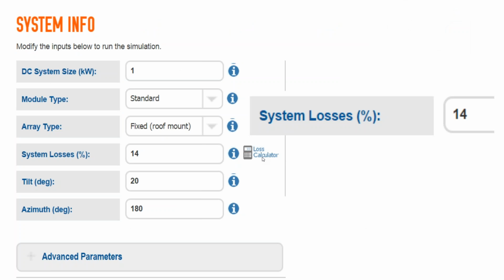So working up to our PVWatts example, here I always do a 1 kilowatt solar array. Again, we create a scalar so that we can do mental math when talking with clients. If you know how much per year 1 kilowatt of solar will produce, then you can multiply by whatever you want when talking about system sizing, or divide by it if you're given an electric bill.